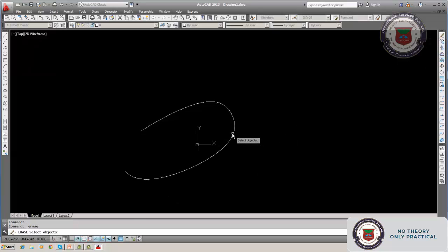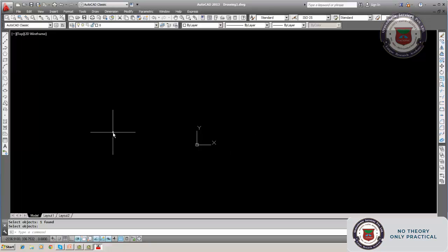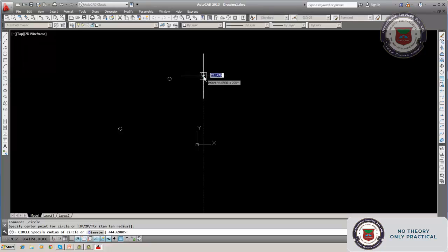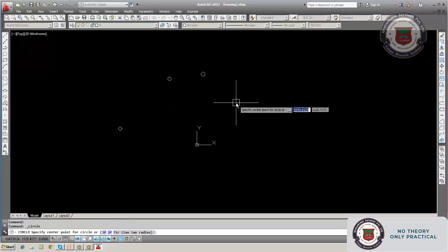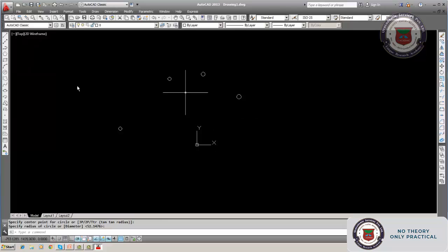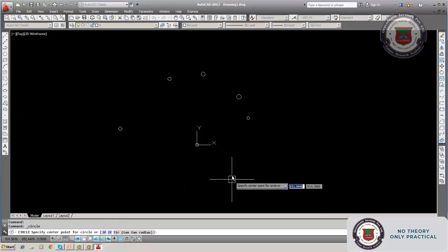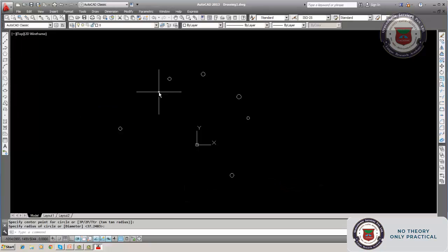For a curve through points, when you do the points and you want a smooth curve passing through 3 points, then you require the point command. Suppose I will just fix the point now. One circle center is 1 point. I will explain what a point is later on, how to draw points and its advantages. See, if there are 3 points, it is an arc of a circle. If it is more than 3, it is a spline. It may be some regular figure. Now I am fixing 3 points as a circle. Now suppose we want to draw a spline passing through the centers of these points.